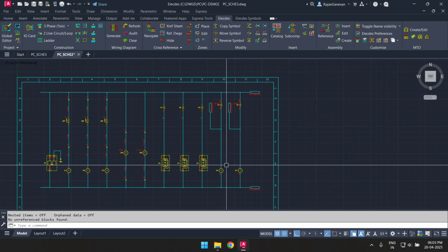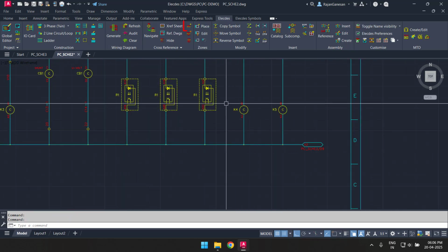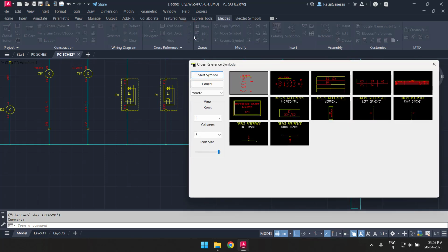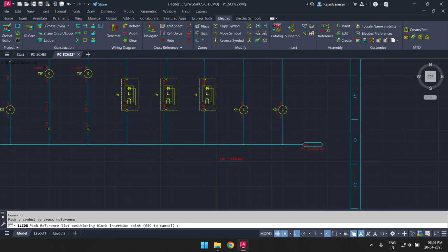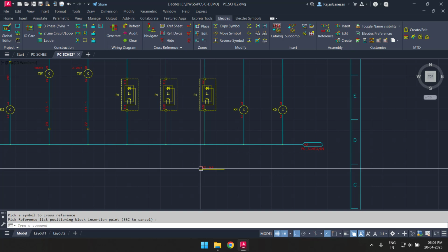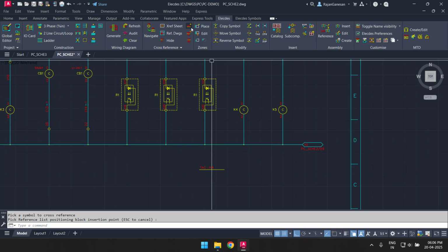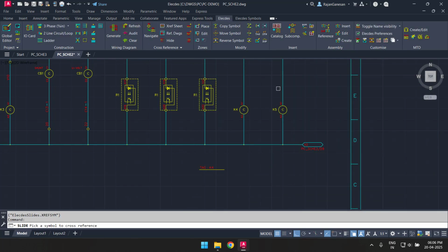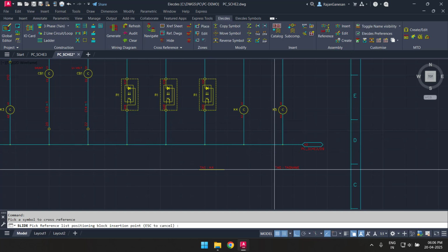Cross-referencing of families of subcomponents often requires a table to be positioned and created. I'll insert a table header. A table header needs to be linked to a component with a family that needs referencing. I'll make a table for the relays K4 and K5. I'll position the headers in the space under my relays. I'll select the cross-referencing tool from the ribbon menu. The cross-reference tool asks me which components and tables I wish to reference.